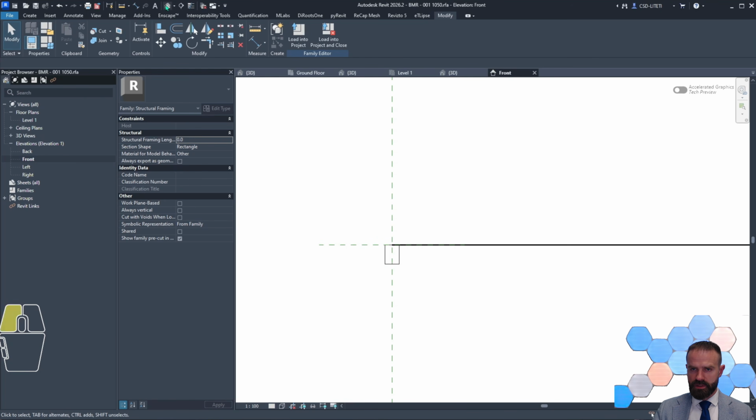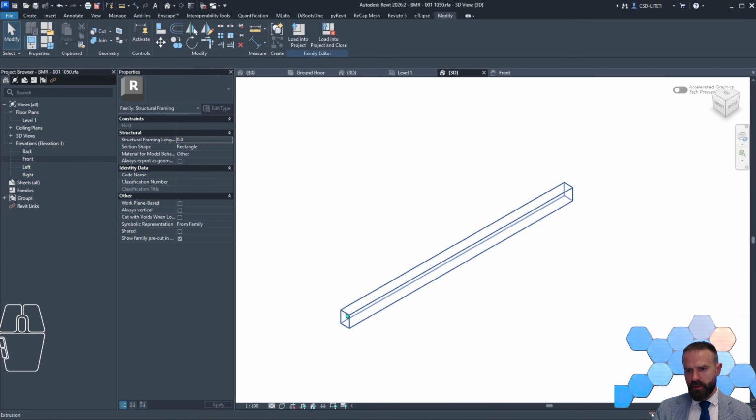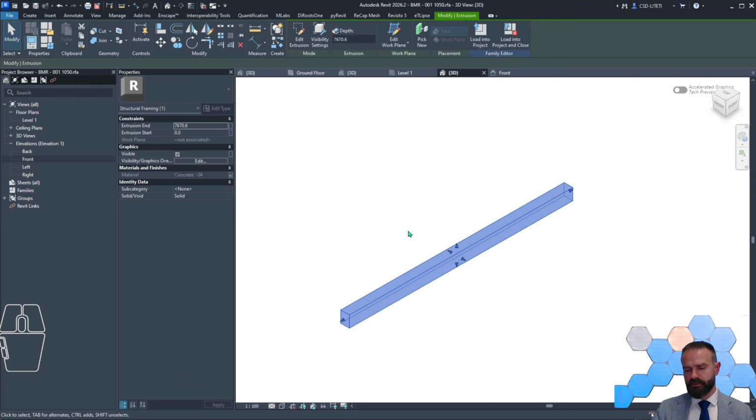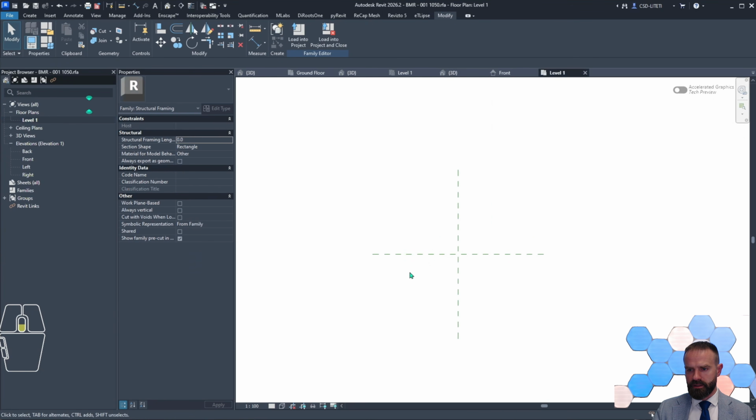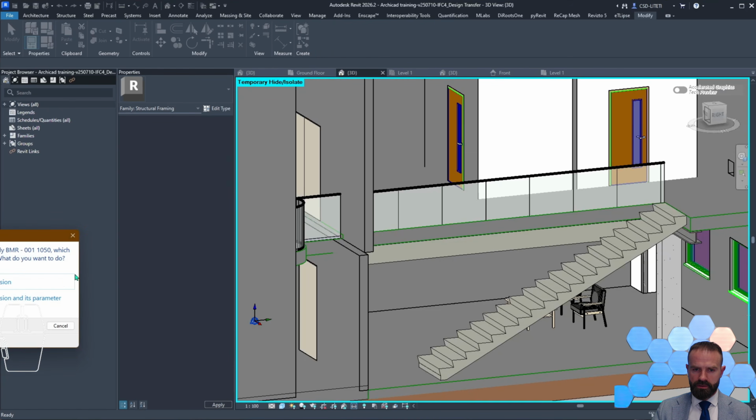so the problem is that inside Revit, all framing elements, beams are created as structure analytical object created by line, and the line is converted to this 3D geometry object. And in this case, it's just extrusion. It doesn't have this line-based component here, and it seems it is an issue compared to typical components.